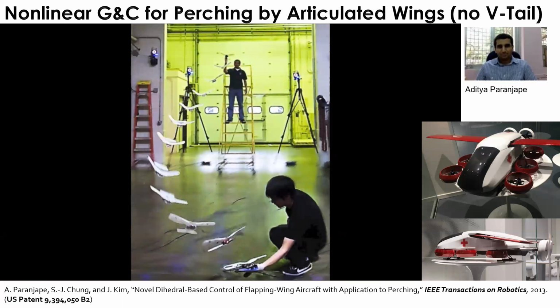Then you find certain paths, and expand the sphere along the chosen path using real dynamics and more rigorous constraints, like I was doing earlier in sequential convex programming. That way you can find an optimal path. So as opposed to drawing a hyperplane approximation with respect to all the different obstacles, you just expand the sphere or ellipsoid along the path. It becomes like a tube, and then you solve the optimal control problem using sequential convex programming.